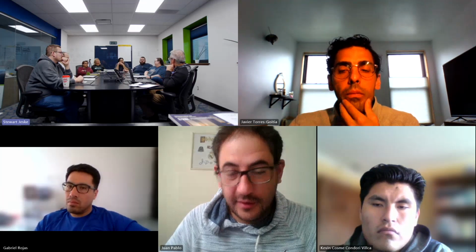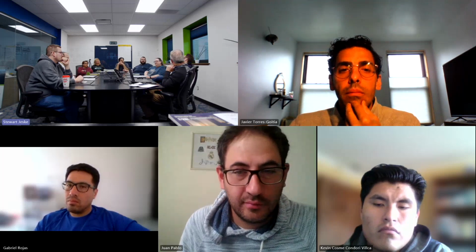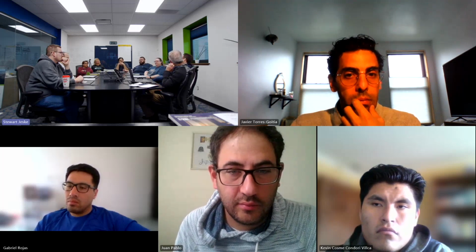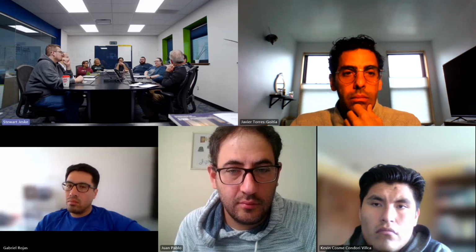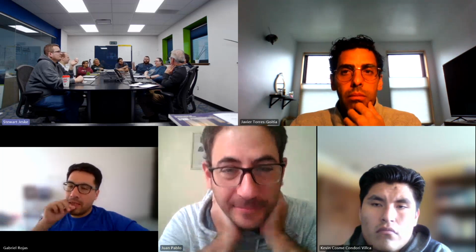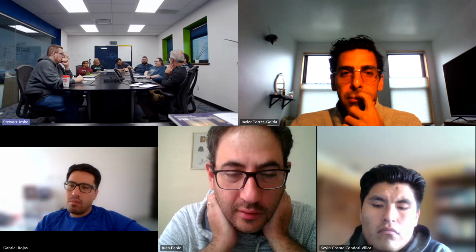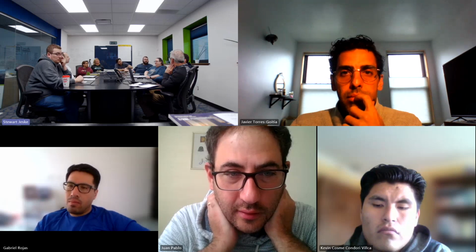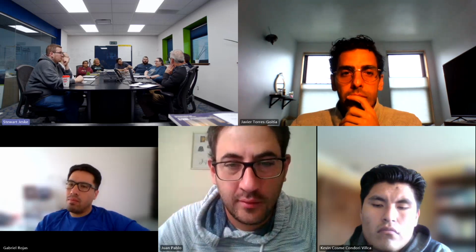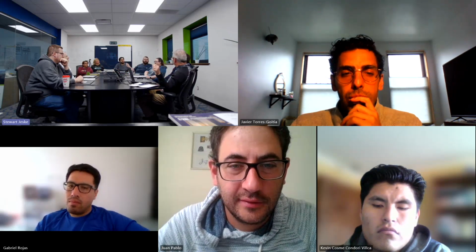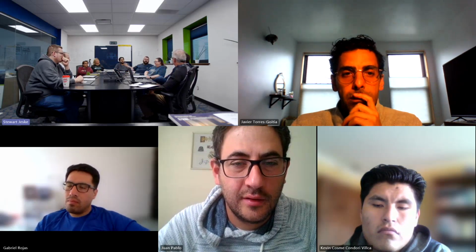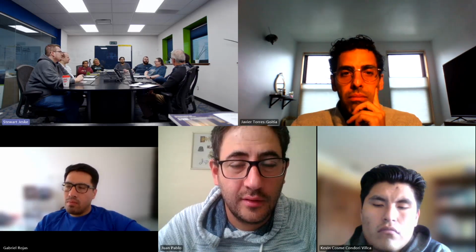Wow. I thought you were going to say that she used the study pressures. No, at least she's conservative. But it's doubling. Because of how she described the other scenarios, where she parts and pieces stuff to get the wind load pressures, for this building she goes, well, because it's so high, I just drew a rectangle around it and treated it as a really wide high rise.